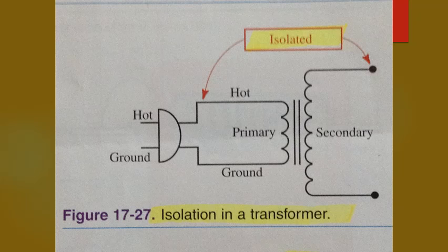One connection is hot, which means that the connection is electrically energized. The other is grounded, or neutral. Standing on the ground while touching the hot connection will result in a shock. Again, this is for the AC primary. Touching the ground connection alone will not result in a shock.